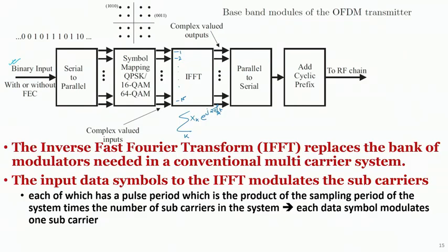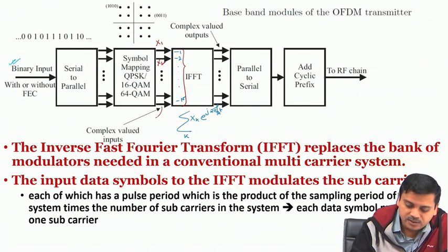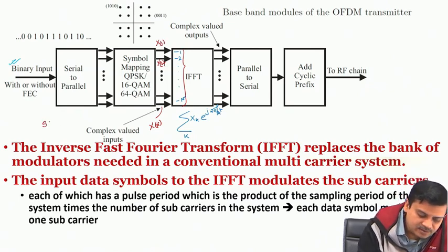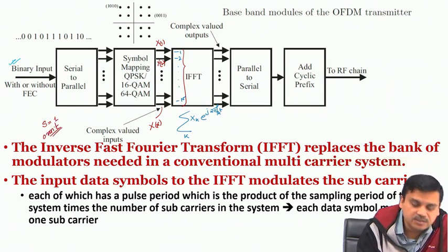Okay. So, now we are back to the transmitter structure. What we see is that each of these is the index of the subcarriers. So, they must be filled with these different constellations. So, here it is x[n]. Rather, as per the notation in this particular slide, s is equal to 1, or we are omitting s for ease.